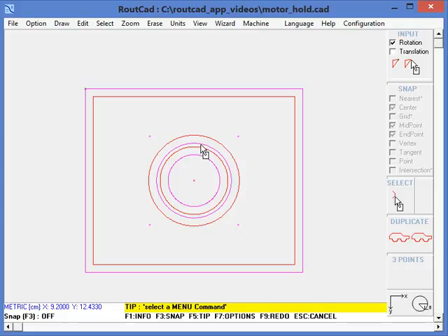The circles in pink represent the counter bore, the first circle, and was offset by also the radius of the milling tool, but toward the inside. And the full bore is another circle that was offset toward the inside by the radius of the milling tool.